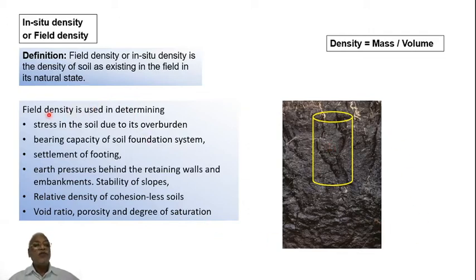Now what is the purpose of knowing the field density? Field density is used in many things. The immediate use is in calculating void ratio, porosity, and degree of saturation. All these terms we have already defined, but these are found indirectly by knowing the density. That's an important application of field density.